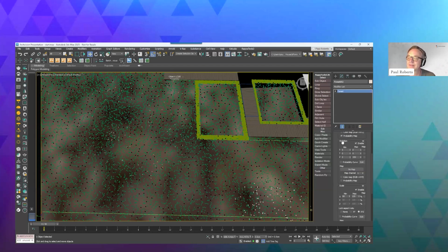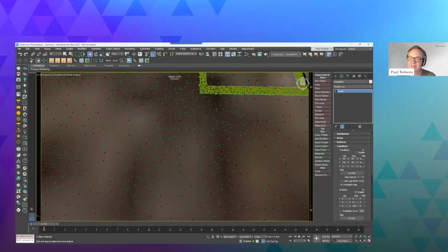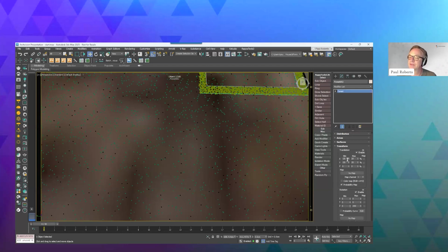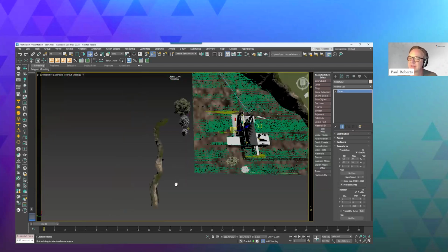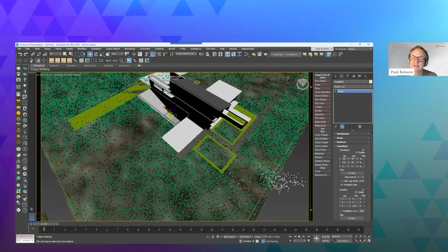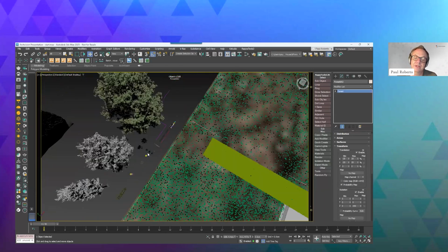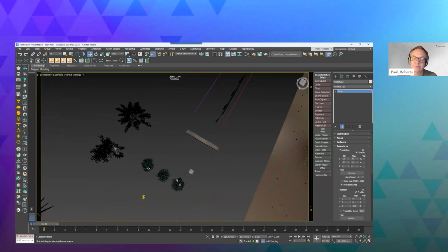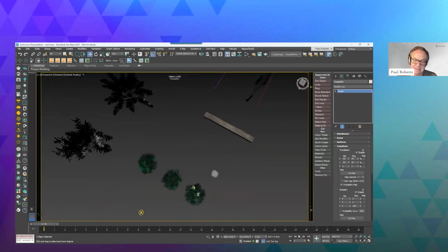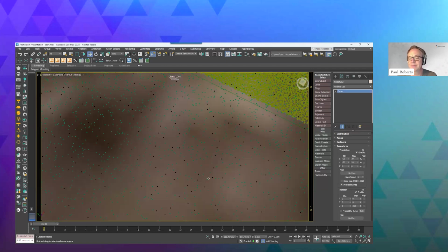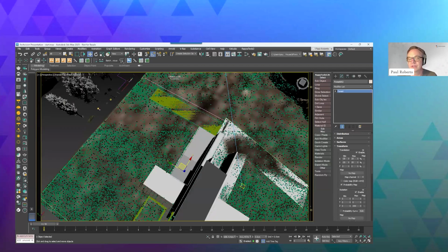Do, however, animate the scale. And crucially, because we created a grid-like pattern, animate the translation a bit. So they'll wobble around a little bit and it breaks up the grid so you don't see it in the renders. And that's pretty much the trick to creating ground cover. So if you've got these patches from somewhere, like maybe from Chaos Cosmos or Megascans or an RPC or something like that, you can very quickly turn them into very efficient ground cover and cover huge areas with it.